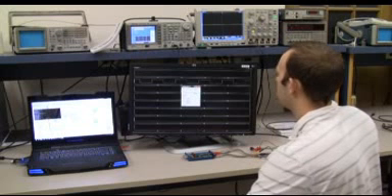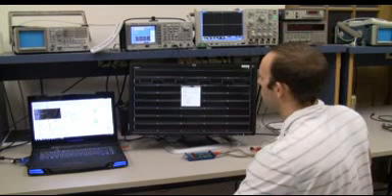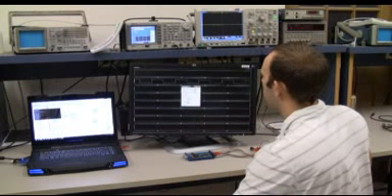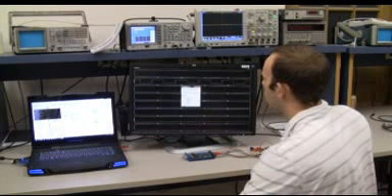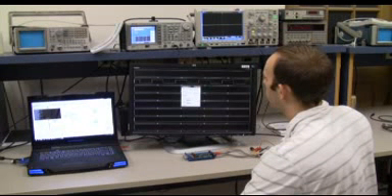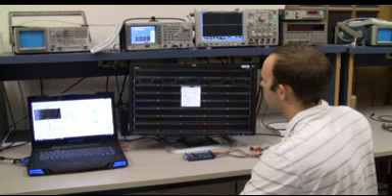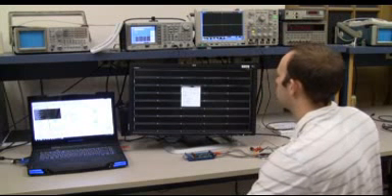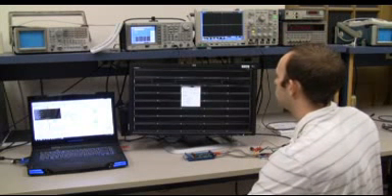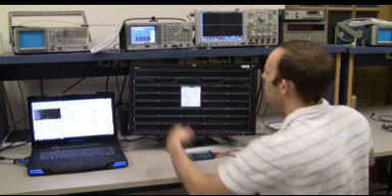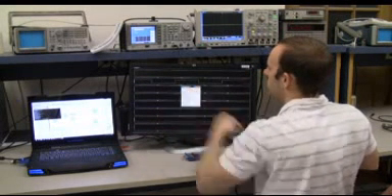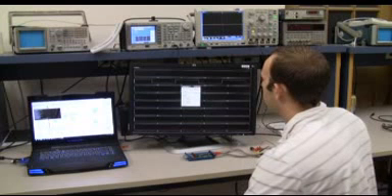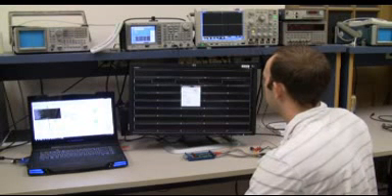Going back to 10 million, we'll now show trigger functionality by enabling the trigger on the rising edge at a 5 volt logic level and using channel 2 at 5 volts to trigger. It will take 3 seconds from now. As you can see, on the rising edge is where it was captured, and if we want to use the falling edge instead, we choose falling.